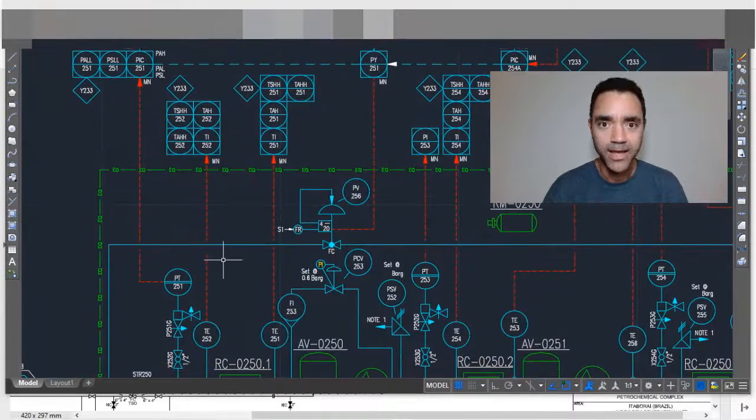In the opposite, as I reduce the value of the process and I need to increase the signal to the control valve, I have reverse action. This is a rule of thumb. This kind of condition depends a lot on whether the valve is fail closed or fail open. It is a good way to identify the action of your control in the piping and instrumentation diagram.